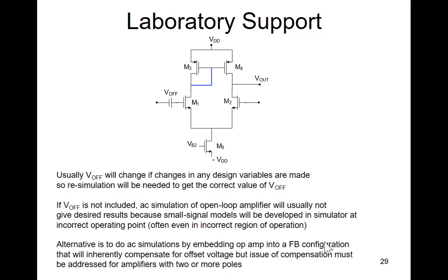Last comment. When you do an AC analysis, can you see distortion in the laboratory by doing AC analysis? By sweeping an input, maybe put inputs at different voltages in and see what the distortion is. Are you with me? Depends what kind of distortion you're looking for. Nonlinear distortion. Generally, if you have an amplifier, the bigger your input signal is, the more nonlinear distortion is present. And so the way you measure the distortion is to put bigger and bigger signals in, and whatever your signal is, you look at the harmonics.